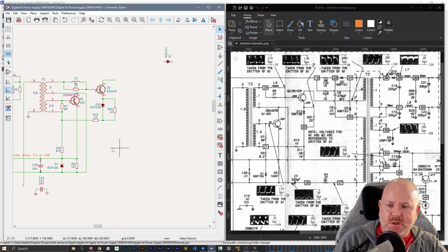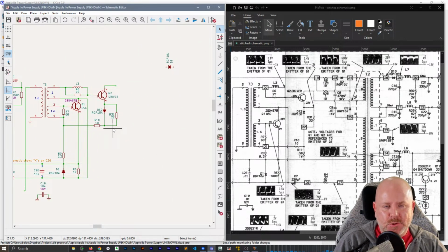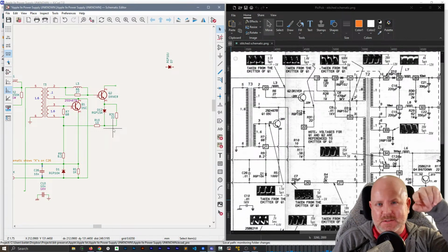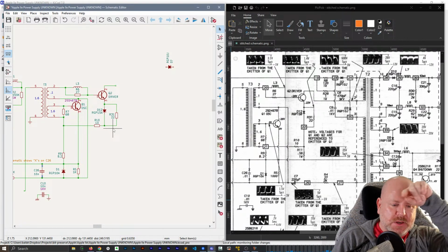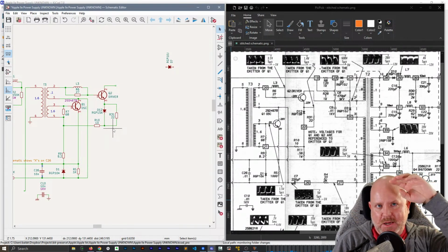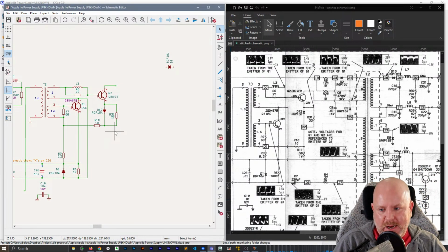Yeah, actually, so the way that the battery emulator worked is it had a 200 point profile, and I think it may have done some interpolation between the points, but it knew that when the capacity was at a certain value, the voltage would be at a certain value, its internal resistance would be a certain value, and it would essentially adjust the load aspect of the box to match those parameters.